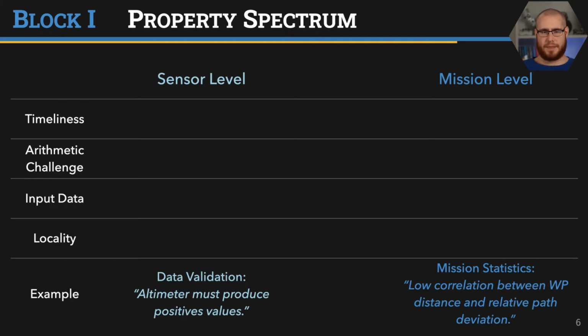Now, an interesting thing here is that the data validation is really time critical. So we get new values from the sensor and we want to immediately get a verdict whether this value makes sense or not. And this information is then used throughout the entire CPS. And if the monitor takes a couple of seconds to decide this, then this value might have already reached the controller and caused a couple of bad decisions. So here timeliness is really critical.